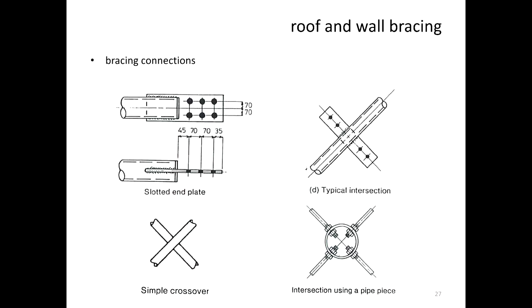Zero eccentricity in your structure, because when you have an eccentric load, that force acting multiplied by that eccentricity generates a moment. And if you don't account for that moment, it can be acting on your structure and can impose additional load that is not accounted for. So that is why we need to understand how these work.